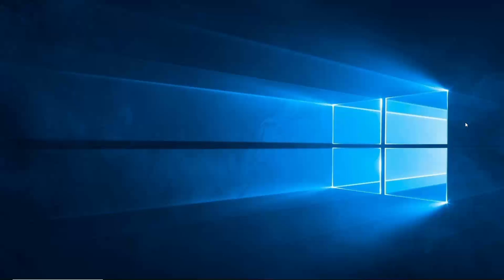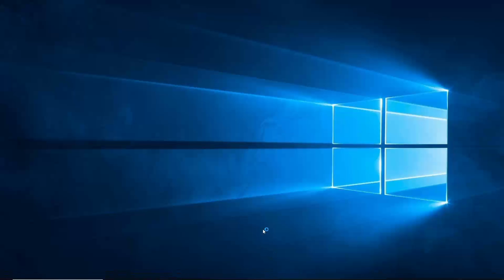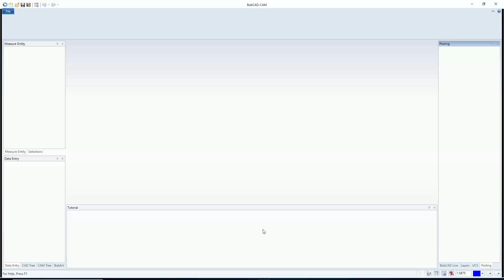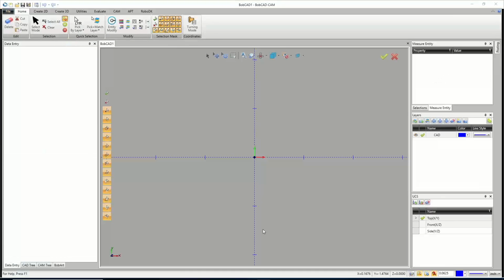David said, so for the slots, if you shorten the ramp radius, would it have spiraled in instead of ramping? Probably. We could try it real quick and see what result we get. But yeah, that sounds like what I would imagine would happen, because I usually use spirals more on circular pockets anyway. But it seems like a lot of times when you're doing a spiral on the circular pocket, it depends on what kind of pocket you're using, I think, too. Like an adaptive might be able to handle it better.